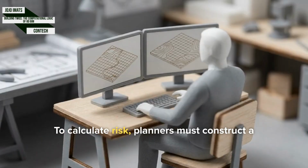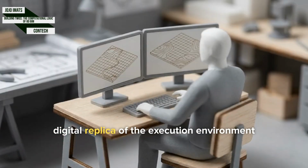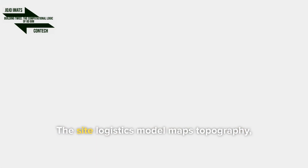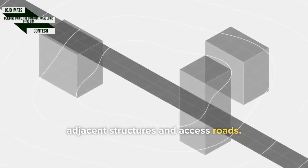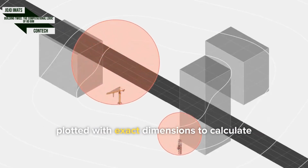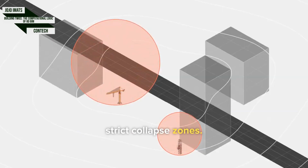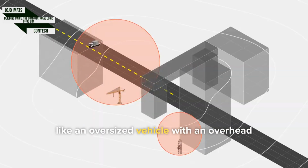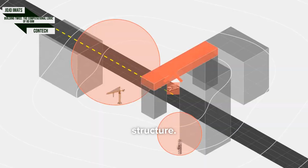To calculate risk, planners must construct a digital replica of the execution environment itself, mapping every temporary element that enables the build. The site logistics model maps topography, adjacent structures, and access roads. Next, dynamic equipment like tower cranes are plotted with exact dimensions to calculate strict collapse zones. Modeling these volumes reveals bottlenecks, like an oversized vehicle clashing with an overhead structure.